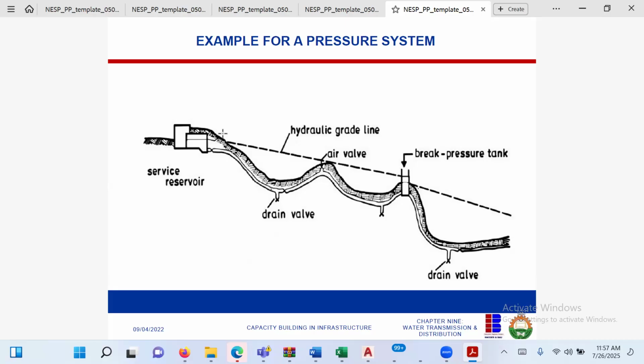You know, South Africa is a mining country. So they've somewhat advanced that after 100 years of mining activity, their groundwater is so contaminated that they are treating them now. So you can see that when they run this pipe like this, you see all these places you have these inflations. They're supposed to be air release valves. Very, very important, air release valves.